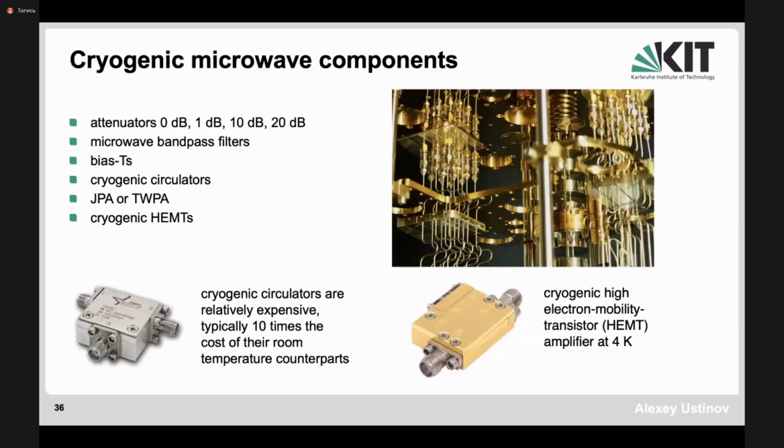Experiments with superconducting qubits require a variety of microwave components. You see these coaxial cables. So these are plates here, which I already mentioned in the previous illustration. These are cables which bring down the microwave signals. Now the cables contain also attenuators, which basically are dividers of the power between the signal line and ground. They are mostly needed to avoid thermal microwave photons from high temperature stages. To cut the noise in uninteresting frequency ranges, one uses also microwave bandpass filters.